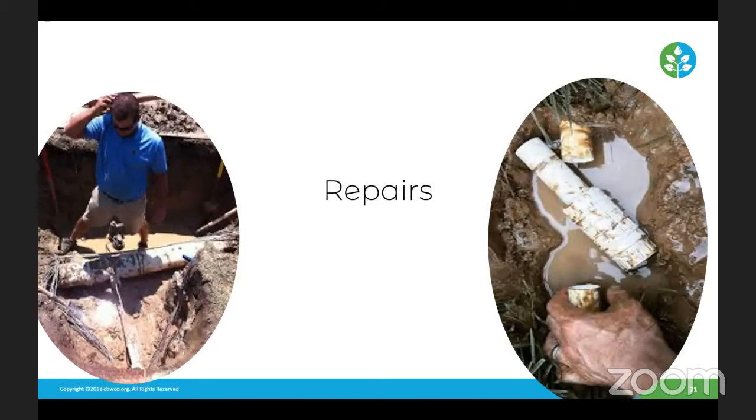So if you do have it leaking, there are a couple options. I would terminate the water pressure to that system completely. So hopefully in your manifold, which again is a grouping of valves, there's a shutoff valve. If you're able to turn the water off so there's no water pressure, I would take that screw completely out and see if there's any damage to it.